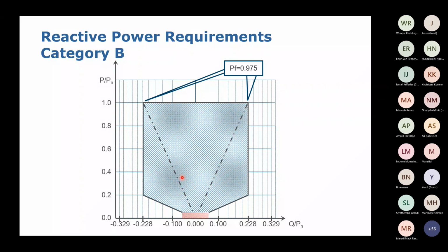One can, from the grid impact assessment, decide what should be a reasonable point for this generator and just inform them to operate there. This is what Eskom in any case does. They seldom do this dynamically. They get a standard set point. This is where you operate 95% of the time, but the system operator can still tell them, listen, please change it now dynamically through the SCADA.